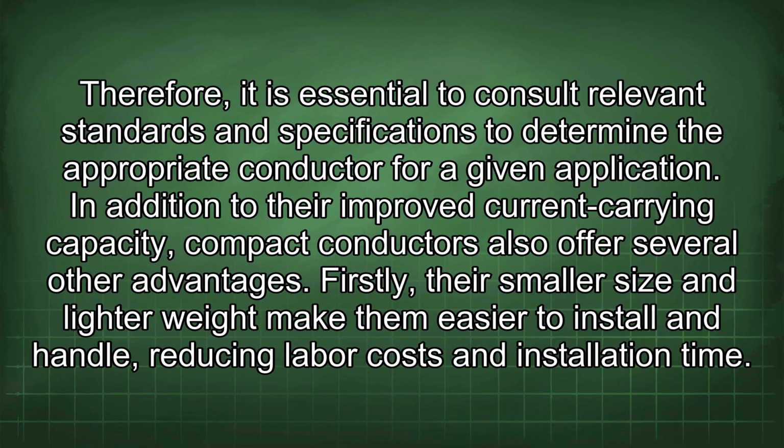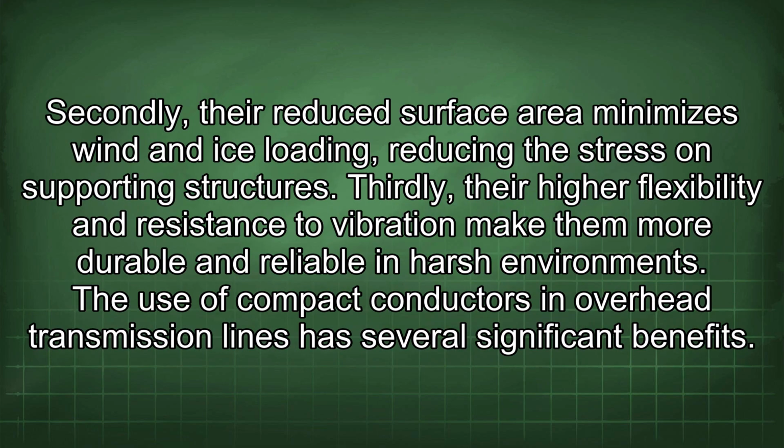In addition to their improved current carrying capacity, compact conductors also offer several other advantages. Firstly, their smaller size and lighter weight make them easier to install and handle, reducing labor costs and installation time. Secondly, their reduced surface area minimizes wind and ice loading, reducing the stress on supporting structures. Thirdly, their higher flexibility and resistance to vibration make them more durable and reliable in harsh environments.